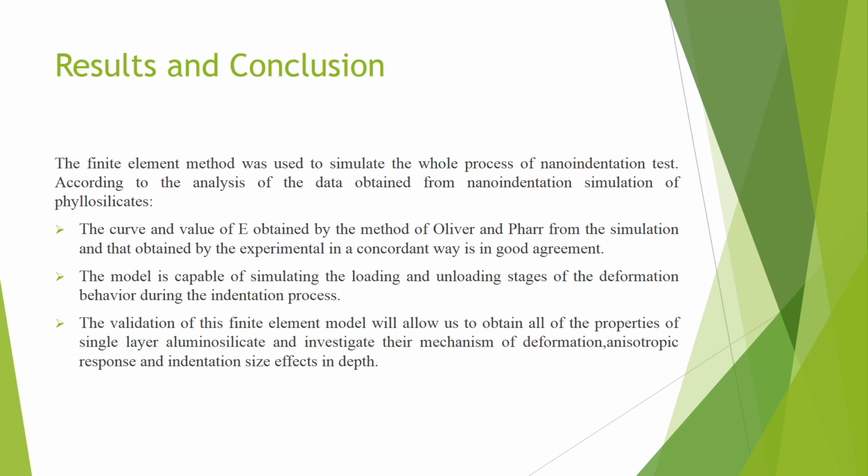The finite element model was used to simulate the whole process of the nano indentation test. According to analysis of data obtained from the nano indentation simulation of ferrosilicates, the curve and value of elastic modulus obtained by Oliver and Pharr from the simulation and the data obtained by experiments are in good agreement. The model is capable of simulating the loading and unloading stages of deformation behavior during the indentation process.